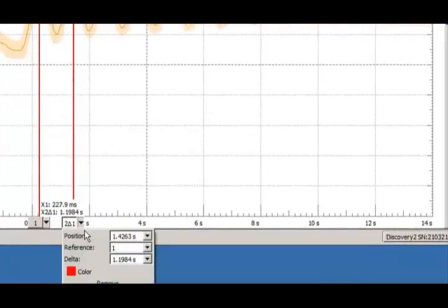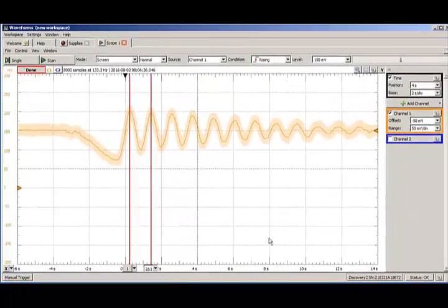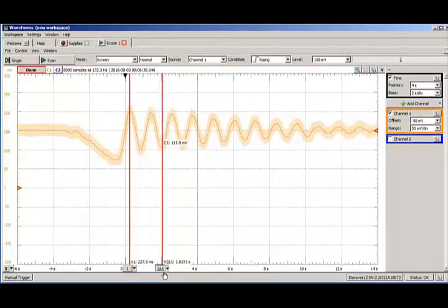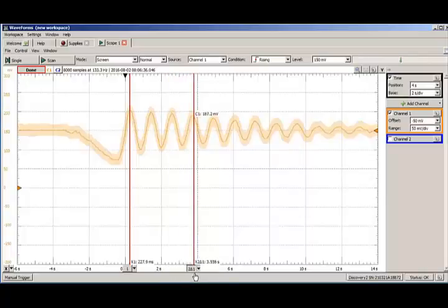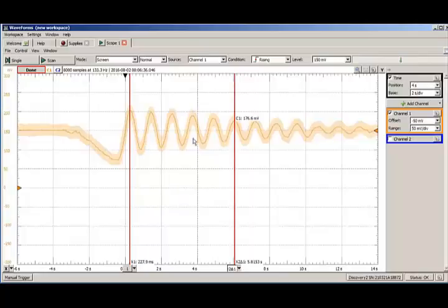So now I can find a difference. So the difference is about 1.2 seconds. So that can give me my damped natural frequency. Now I need a damping ratio. So I need to get the value of the function at 2 successive points. In order to get a little bit better response, I think I'll go 3, 4, 5 periods. Averaging across 5 periods will probably give me a slightly better estimate of the damping ratio.